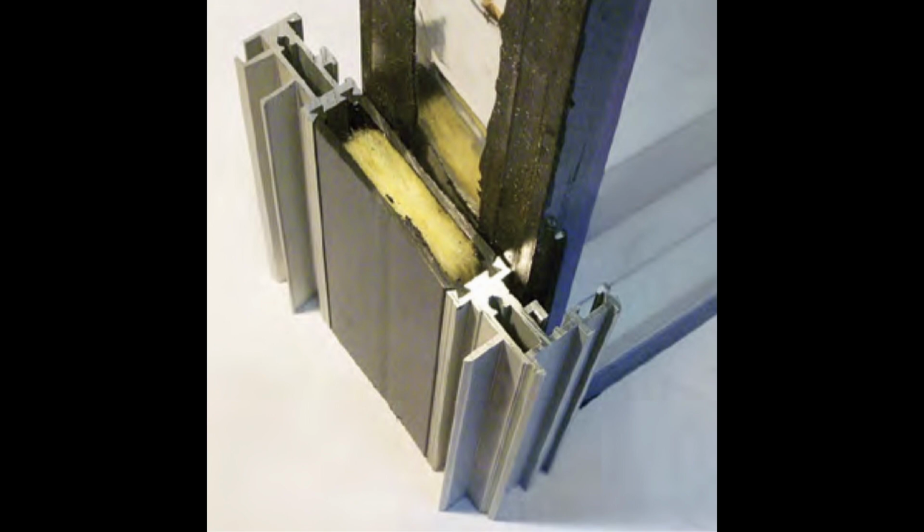But a downside to aluminum is that it can conduct heat pretty rapidly. So unless there is a thermal break present, the window will be thermally inefficient and at risk of what we call condensate or frost. These types of windows are also more expensive than wooden windows. Those are the disadvantages of aluminum windows in comparison to wooden windows.